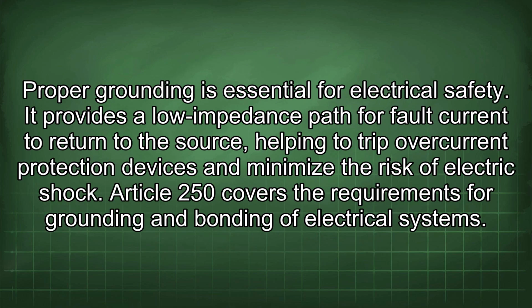Proper grounding is essential for electrical safety. It provides a low impedance path for fault current to return to the source, helping to trip overcurrent protection devices and minimize the risk of electric shock. Article 250 covers the requirements for grounding and bonding of electrical systems.